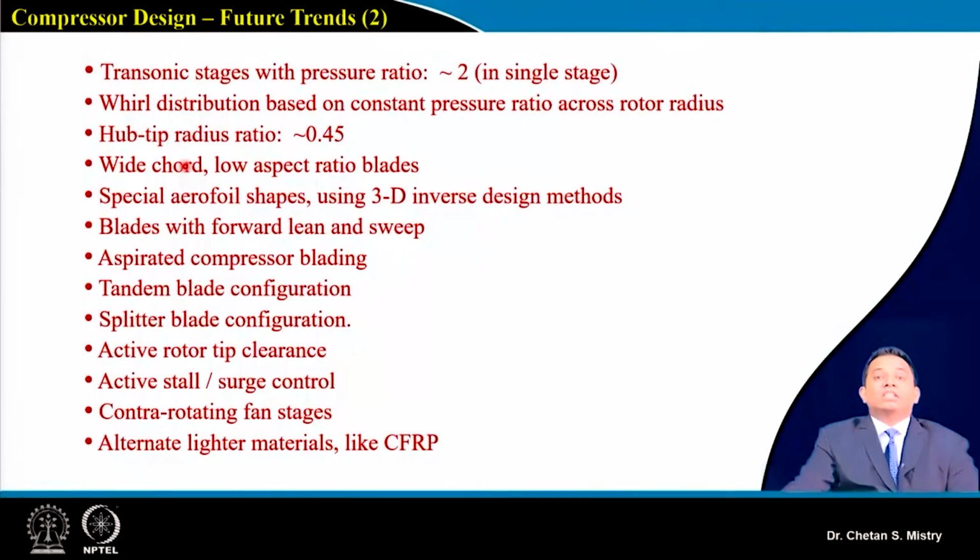And in a very recent engine, in one of our lectures we discussed the GE Honda turbofan engine, in which we have a wide chord fan, and that too a small fan, that is used for business jets. So such kind of design configuration is now in demand. There is a demand for special kinds of aerofoils, say 3D inverse design methodology people are opting for. That is very challenging to accept at this moment.